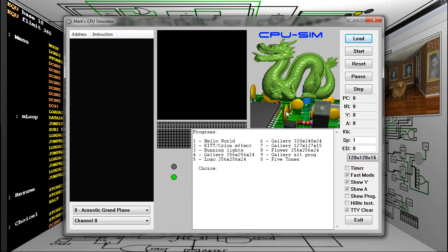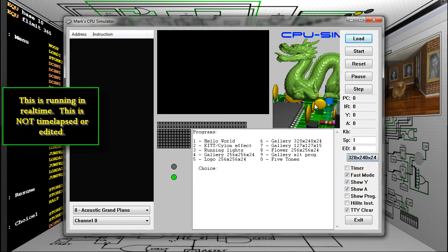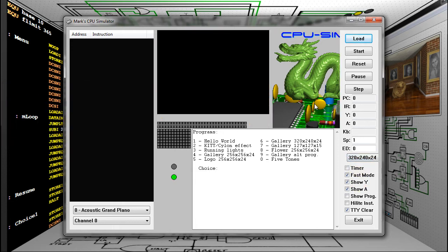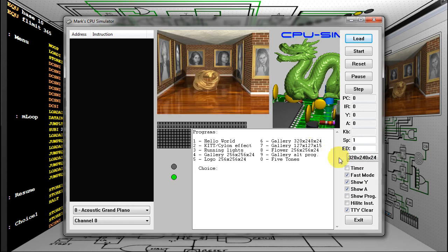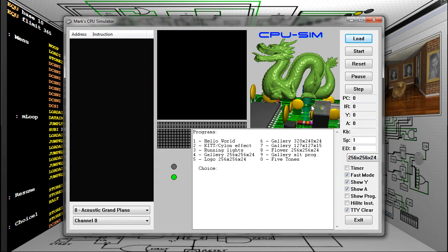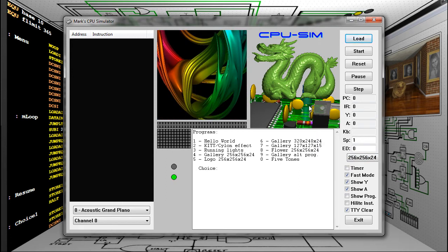One problem with only having the Logisim, VHDL, and Verilog simulators is that they all depend on the designed wiring and electronics. Let's say you write an assembly language program for the CPU design and it doesn't work. Is it because the program has bugs? Or the hardware design has bugs? It might be hard to track down, especially since the wiring might all be correct, but quirks of gate delays and timings might be screwing it up. Especially true if you actually put it in an FPGA.